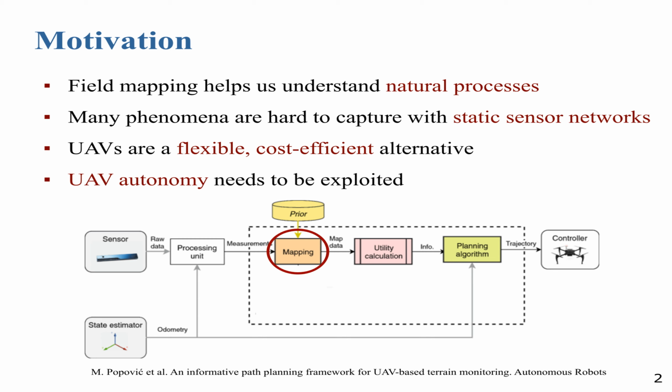Different from manually controlling the UAV for data collection only, we aim at exploiting the autonomy of these platforms, so that the UAV can monitor the fields in an autonomous and targeted way, such as gathering information from regions of interest. Following this idea, we use new sensor data to update our map and replan UAV paths based on the current map state, in order to maximize overall information gain given limited operation time. In this work, we develop an online mapping strategy that can cater for such robotic applications.